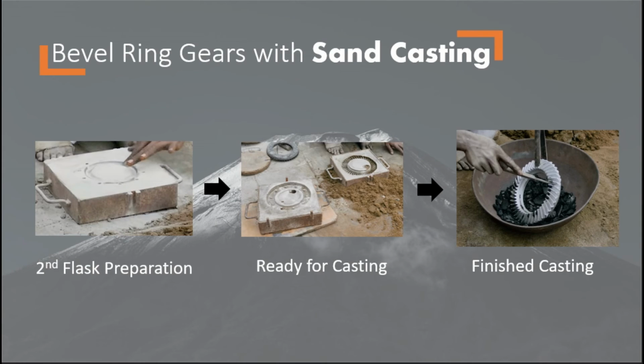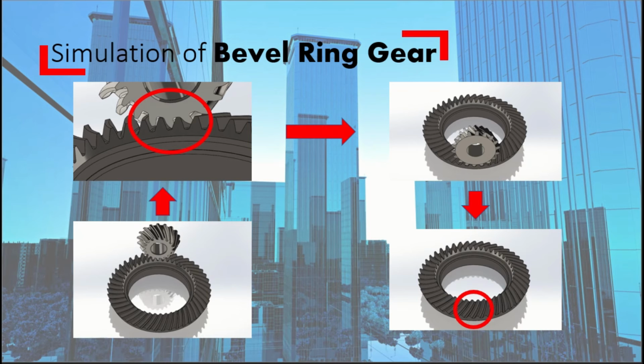This topic is the simulation of the gear in a differential. Both gears actually use the same material and do the same type of work, which is using the teeth of the gear to transmit motion energy. As the slide shows, the simulation will be simplified by using only the bevel gear and applying the force of torque to 3 faces of the teeth. Only 3 faces are selected because the pinion and bevel gear only have a maximum of 3 teeth interacting at the same time. Next,